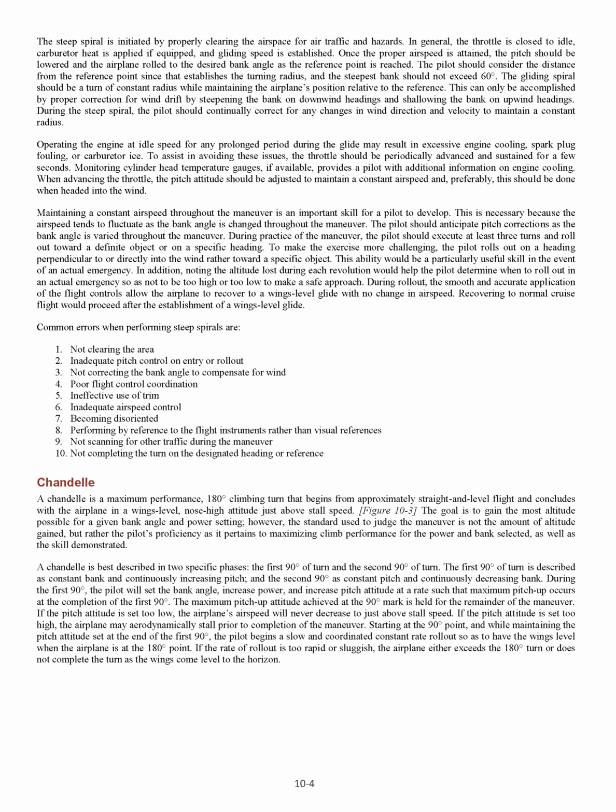During practice of the maneuver, the pilot should execute at least 3 turns and roll out toward a definite object or on a specific heading. To make the exercise more challenging, the pilot rolls out on a heading perpendicular to or directly into the wind rather than toward a specific object. This ability would be a particularly useful skill in the event of an actual emergency.